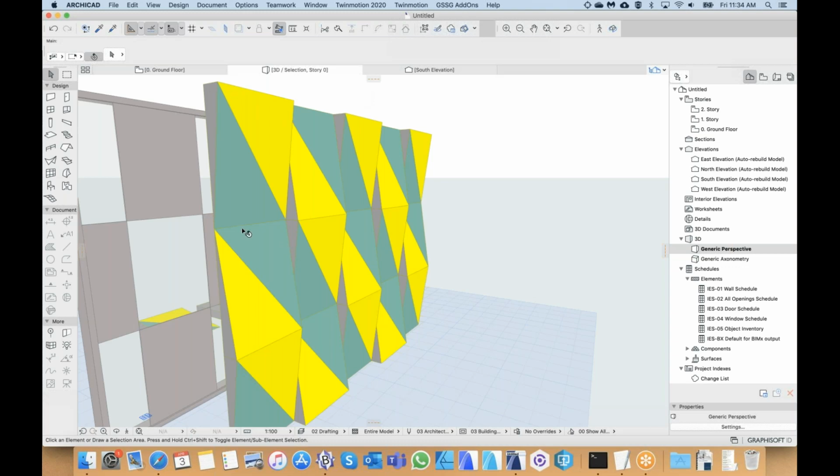So when you create these custom panels, because it's 1.5 by 2 meters, this panel always fits and stretches to the size of your panel curtain wall. So if these columns were, say, 3 meters wide, then this panel will stretch to fit that panel size. So this is why we tried to keep the panel sizes exactly the same as the object we saved.